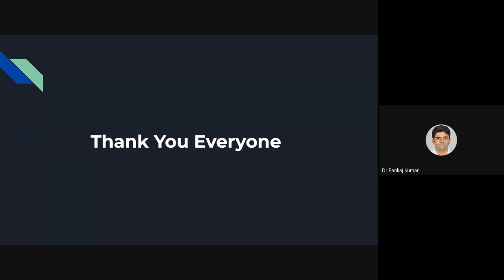For that, did you introduce some friction data, or do you directly apply surface to surface interaction? I directly applied a predefined surface to surface interaction, and I just selected the master surface and the slave surface. The Abaqus software automatically determines the amount of friction that is needed for our calculation.